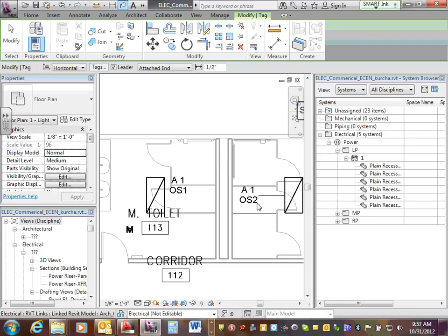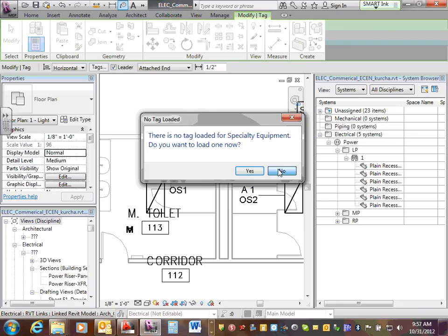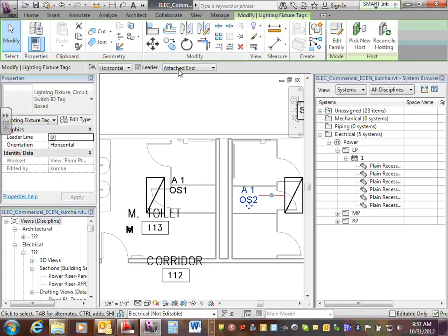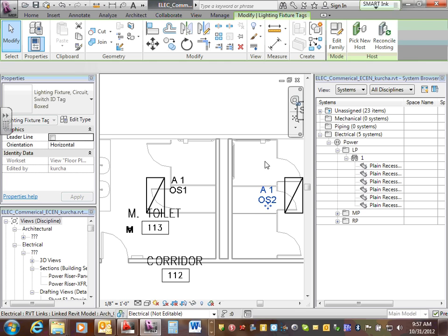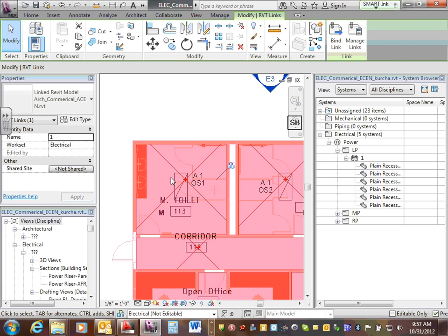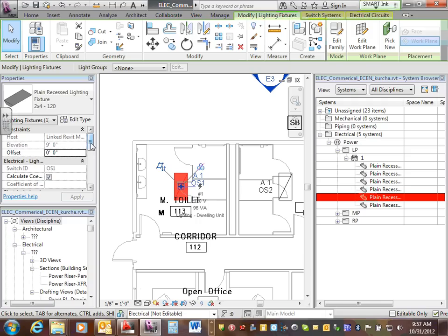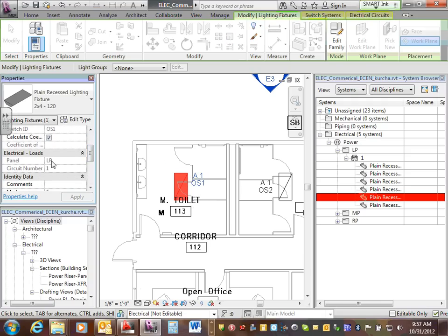The circuit, you must have circuited from the receptacle panel. Jeff, click on the fixture and see where the circuit is coming from, please. Can you see where it says panel here? Is it LP or RP? LP? Circuit 55. Interesting. Jumped all the way to 55.